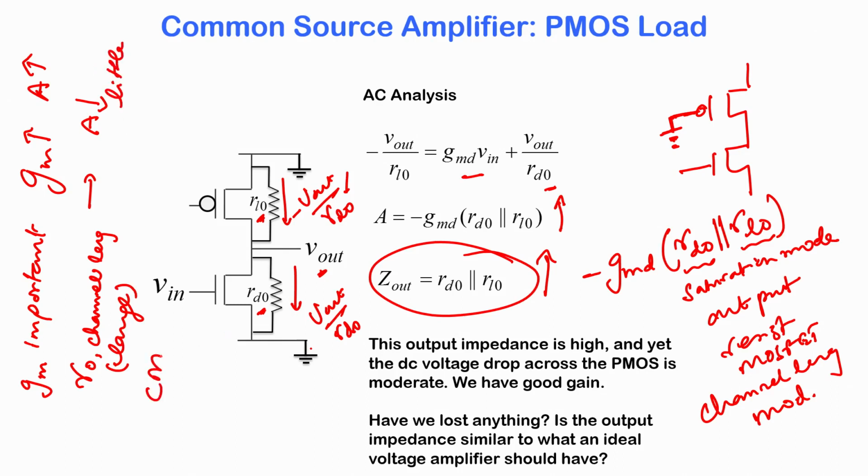And CMOS technology can give you very high gain, and the gain for most voltage amplifiers is a combination of the effective transconductance of the driver and the effective output impedance of the circuit. So, this is the take home message from everything that you have learned.